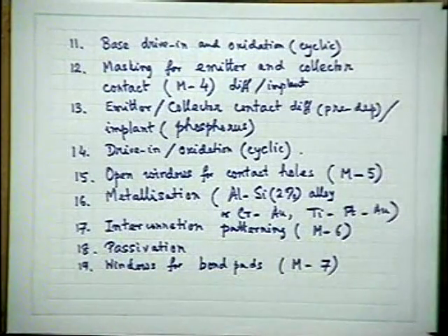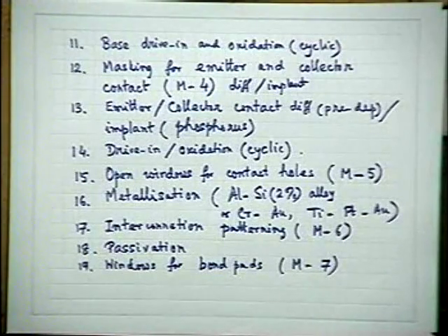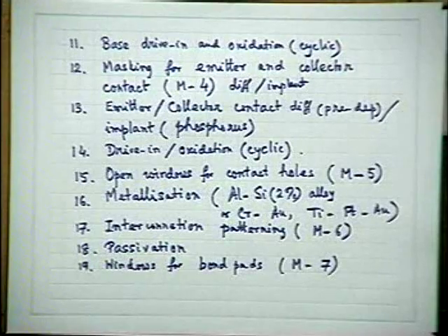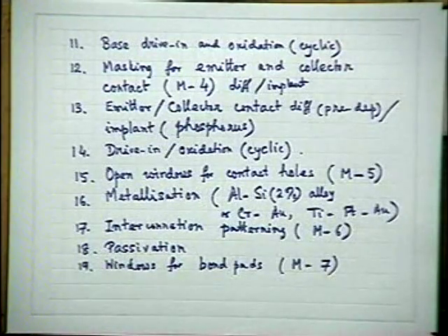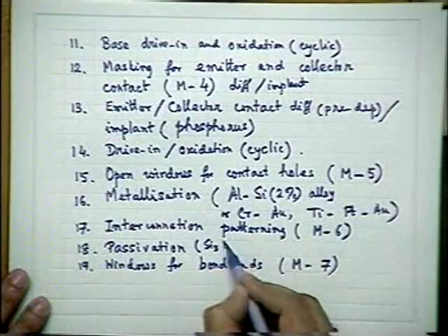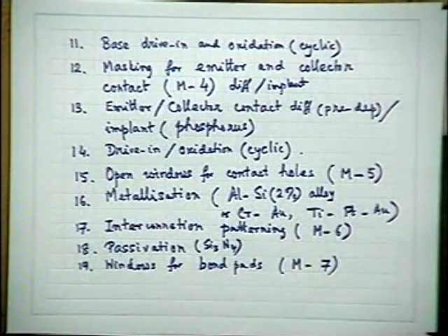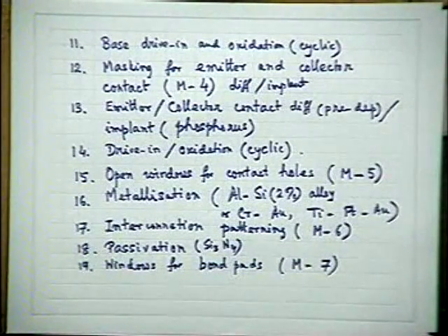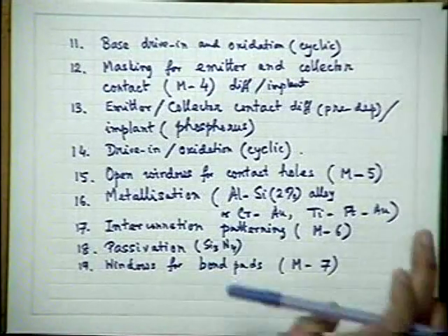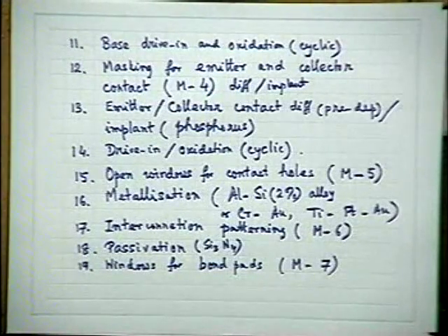After the IC is fabricated, the entire metallization, etc. is done. Then you deposit a very good quality dielectric film to protect the IC from environmental hazards. Usually silicon nitride, passivation; today, modern silicon nitride film. Earlier people also used phosphosilicate glass, but today silicon nitride is very typical.